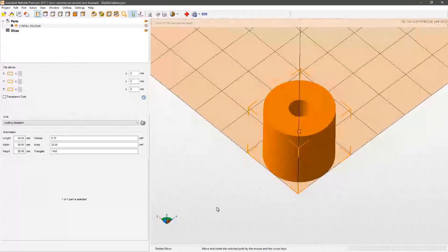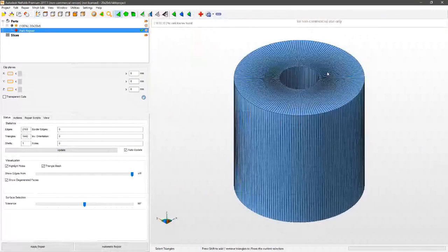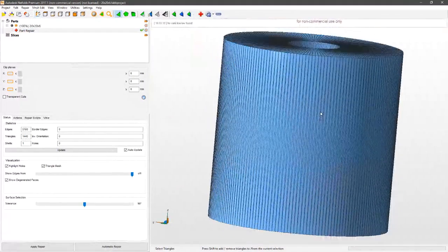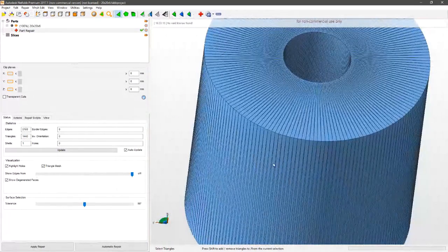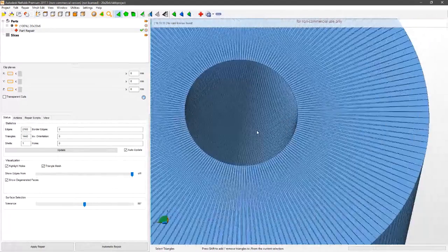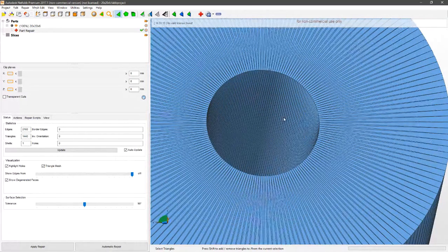So that's a very simple cylinder standoff that I printed today. I needed four of them, didn't feel like making them on the lathe, so printed them. Why not? If we head over to the repair mode, we can actually see the individual triangles. The thing is, an STL can only approximate round surfaces. So the outer curved surface is split up into a huge number of individual triangles. That's not that much of an issue, but when you go to the inside holes, these are much finer segments, and each of these segments is straight when the printer prints it, but it requires the same amount of processing power, the same amount of bandwidth when it comes to the communication between your host, your Raspberry Pi or 3D printer or whatever, and the firmware.